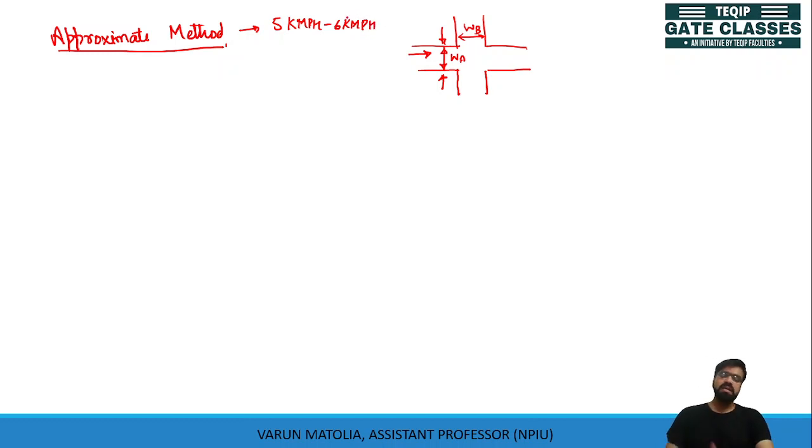To accommodate the unhealthy or the aged or the slow walkers, the value which is taken for pedestrian design is 1.2 meter per second. This comes around 4.5 kmph, or less than 5. So this value is taken as the speed of pedestrian.